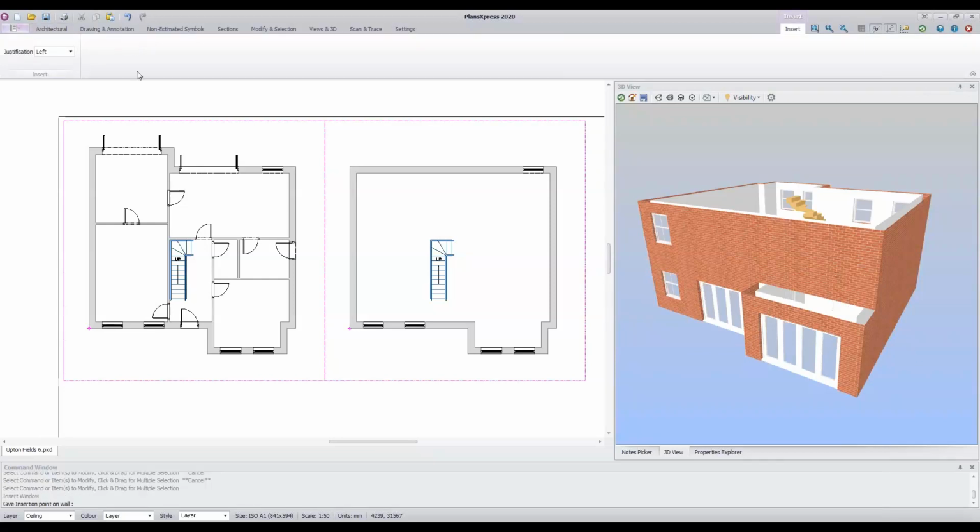It will automatically select the same type of window as we've already drawn, assuming that's the last type of window you've drawn. If you have drawn something else, if you've put a bay window in, for example, it will bring up the bay window specification, whatever is the last window spec you selected. So we said this window wants to be 665mm from the back left corner of the house. So I'll just go through the window placing options again.